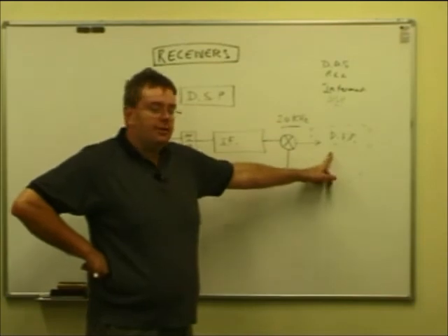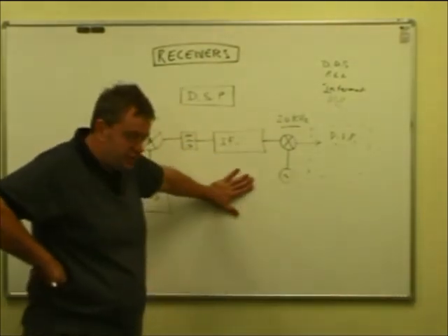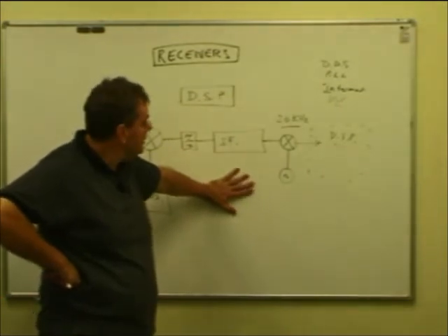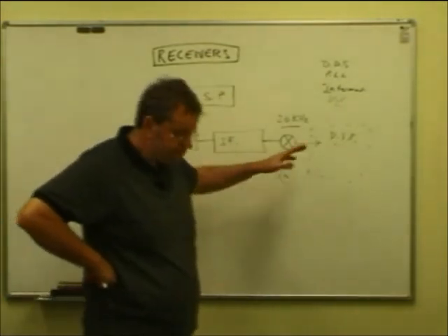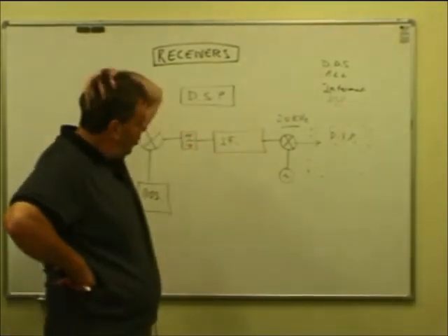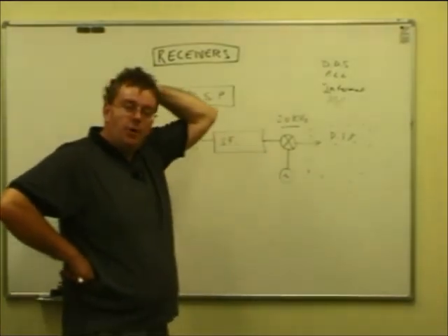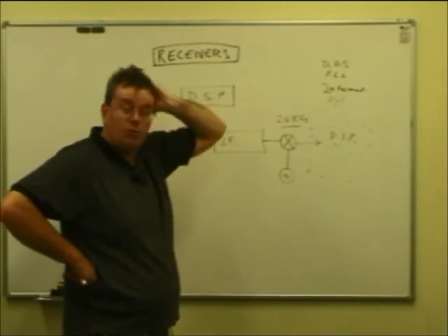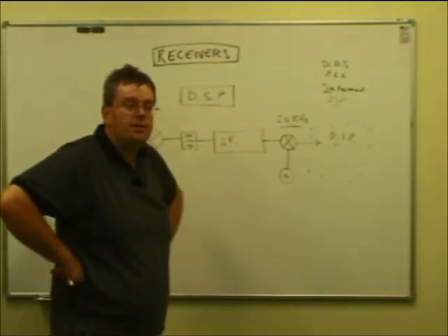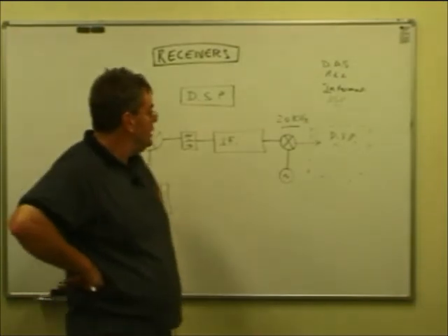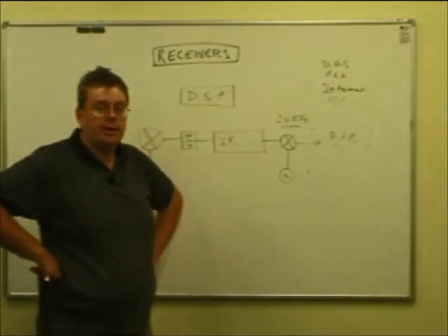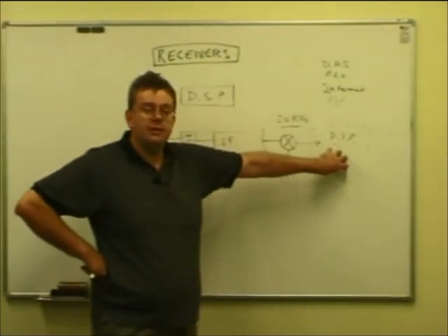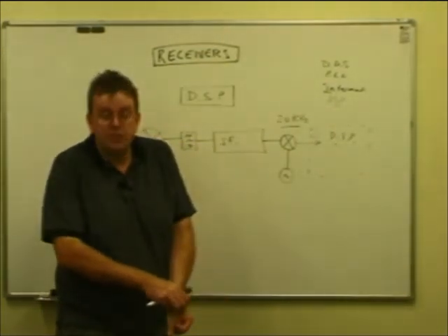And what's done now, this is a spooky thing, is that often the detection, the demodulation, the removing of an SSB signal, getting the sound out of it, or turning a pulsed carrier on and off into beeps for listening to Morse code, or frequency demodulating or discriminating FM, is no longer done by product detectors and carrier insertion oscillators and so on. A lot of that technology is actually done digitally.